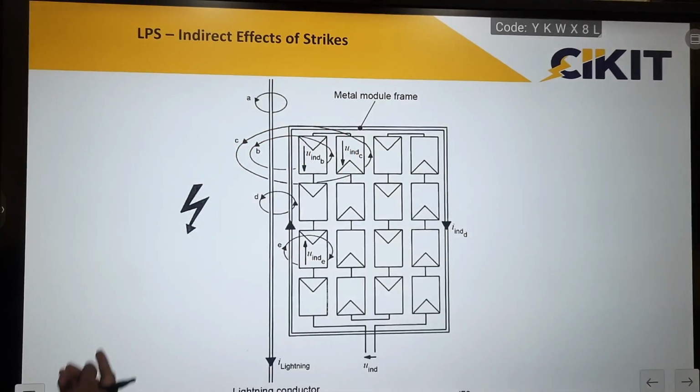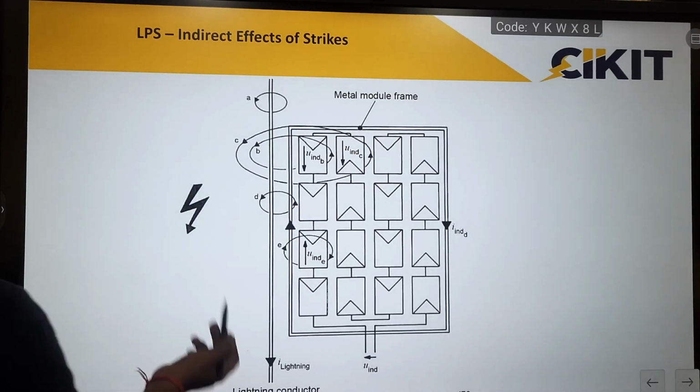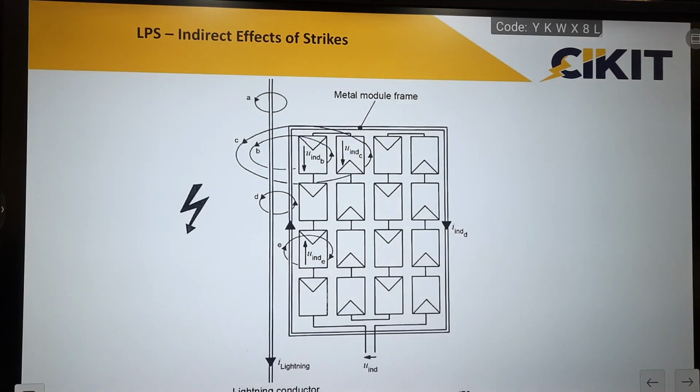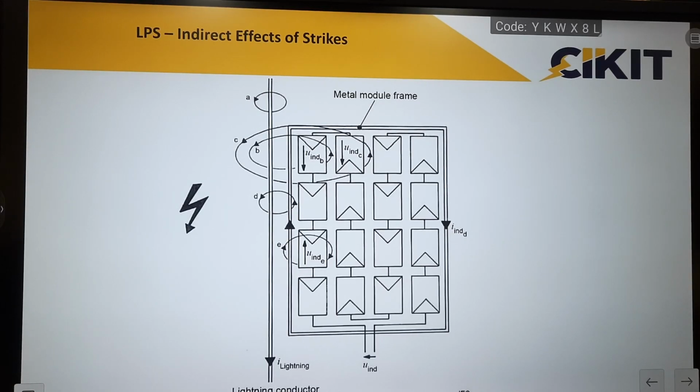So this can be avoided by providing sufficient spacing between this ground conductor and the metallic plates. If sufficient spacing cannot be provided, then in that particular case, we have to go for equipotential bonding. In equipotential bonding also, some portion of the lightning impulse current will flow through these metallic enclosures, and the protection system has to be designed by considering this impulse current also.